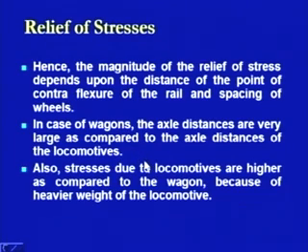And in a similar way, the stresses which are caused due to the locomotives are obviously higher as compared to the wagons, because the weight of the locomotive is much higher. So, when we are trying to find out the track modulus, or the stresses being induced in any component of the track, what is important is the locomotive.